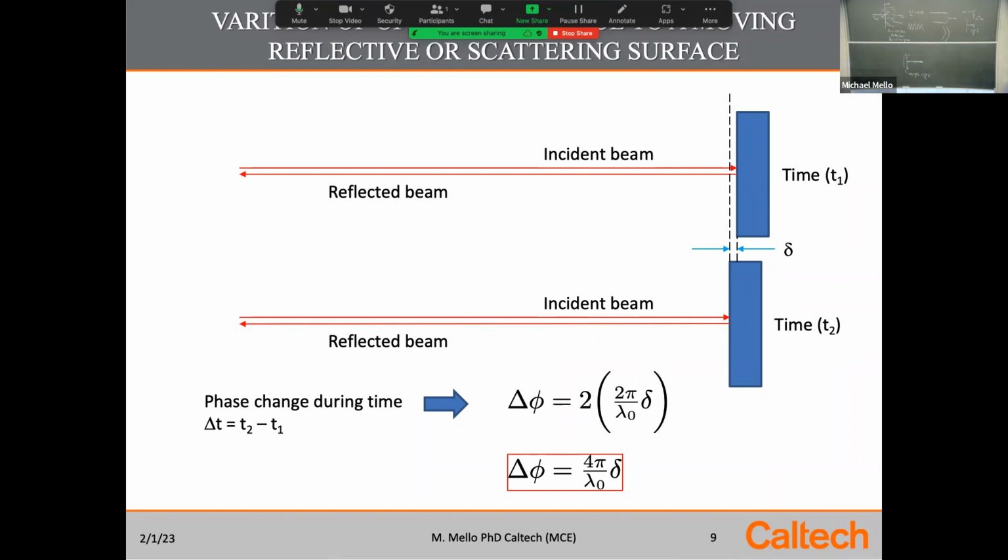Why we would care is because, go back to the cantilever that I showed you on the first slide. The surface is moving, right? There are many of these repetitively happening, right? It's doing this to the laser beam, and we're saying we're shooting that laser beam at it and down, and that phase is being recorded, okay? This phase is being recorded continuously, and the gap is changing with time because the beam is decaying in its vibration, right? So we're plotting this somehow internally in the device because the device can track phase, okay?